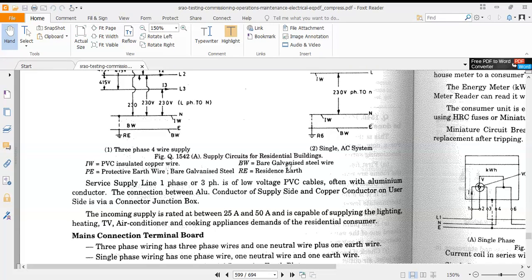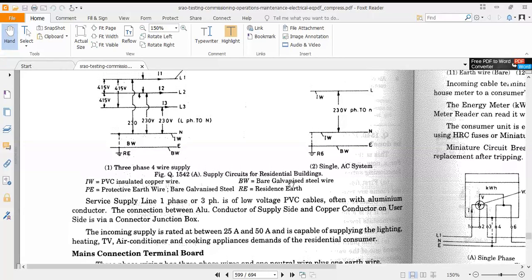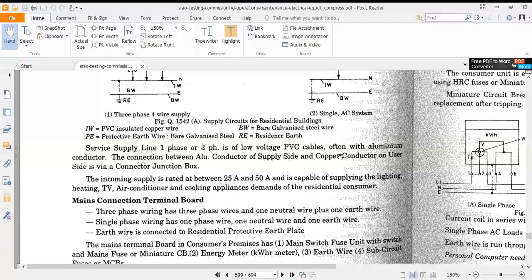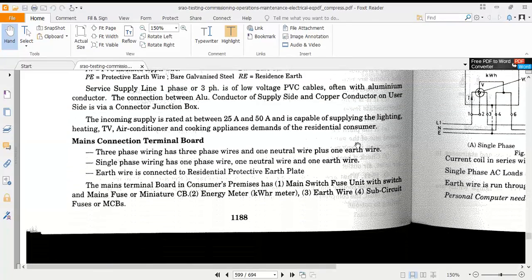If you raise your head and look at the wires running between two poles, if there are only three wires, then you can call it a three phase supply being carried. And if you see four wires, then it is three phases and one neutral. So whenever you come out of the house and go on the street, just look at the wires and you'll make out what is what.